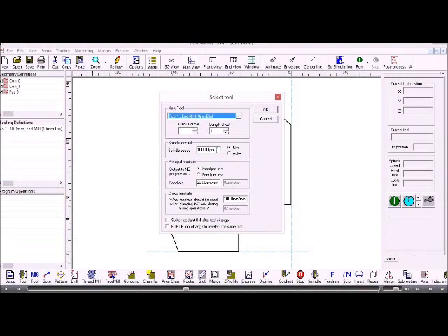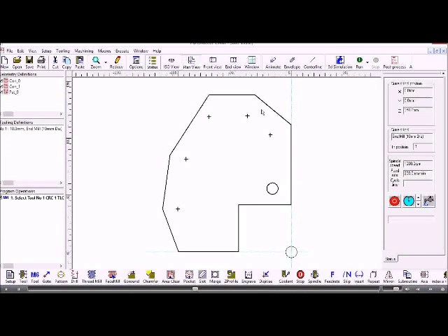The spindle speed, this is where you set it here, pretty much always going clockwise. And we've got two feed rates. The principal feed rate, in this case in X and Y, can either be expressed as feed per minute or feed per rev, and the Z-axis feed rate is what will happen when the tool plunges down in the Z-axis. If you want to switch on the coolant, this is where you do it. So that's selected that tool for use.